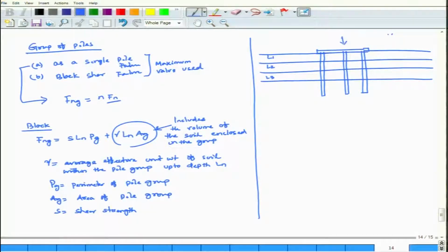There is a capacity here. So, this is the strata, there is a fill soil, there is peat. L1 and L2 are acted upon by negative skin friction. If you look at the direction of frictional resistance, here it is in the direction of the load.